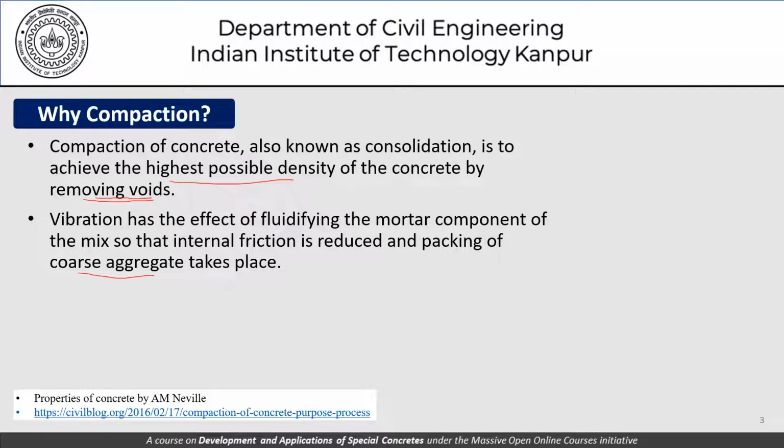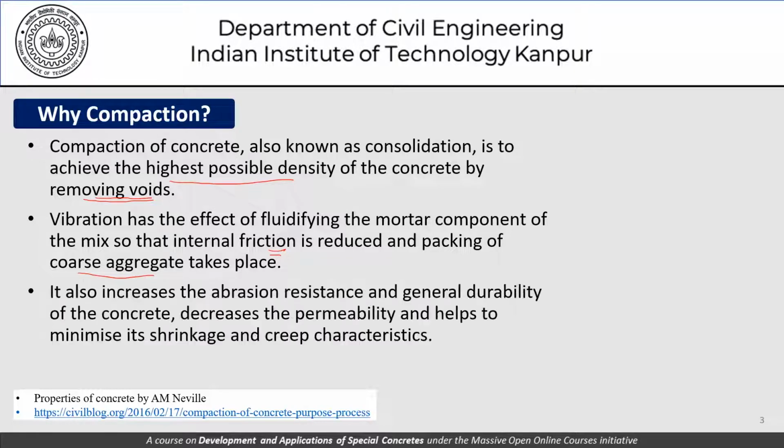So we shall see that actually the consolidation process takes place in two steps. But what is summarized here is that vibration or consolidation has the effect of fluidifying the mortar component of the mix so that the internal friction, primarily between the coarse aggregates, is reduced, and the coarse aggregates take the configuration of greater compactness.